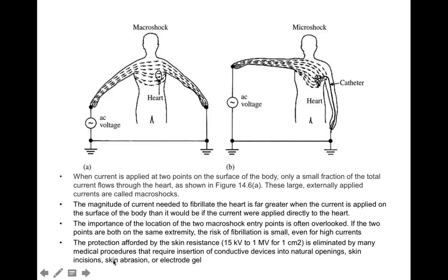If you have skin incisions, skin abrasions, or gels present for an electrode, those are intended to lower the resistivity of the skin. So when you do that, you definitely have created a situation where this natural protection of the skin is reduced.